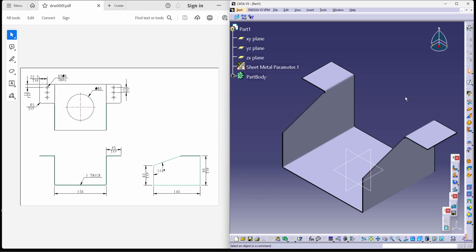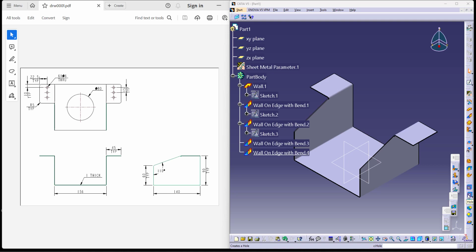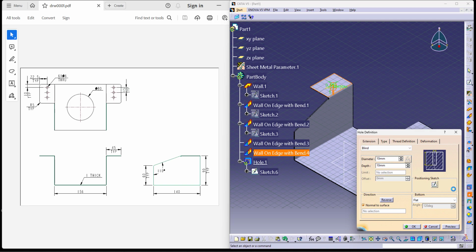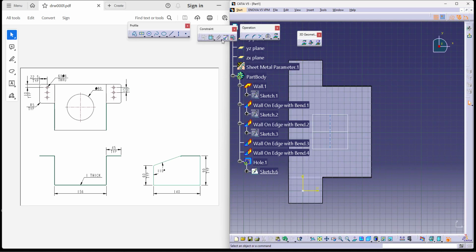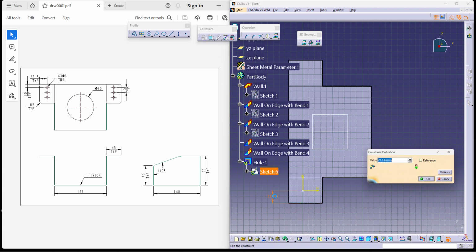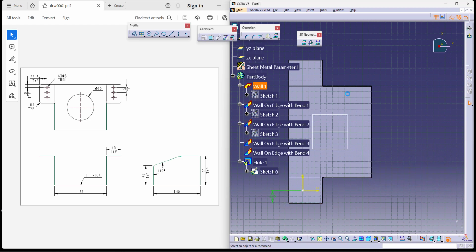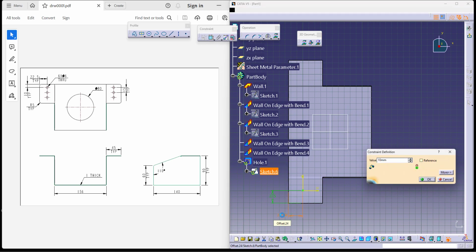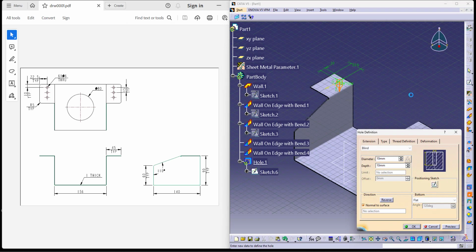Now there are few holes given on the wall for clamping purposes. So let's try to give those as well. I'm just using a hole command. Okay, let me select the face first and then select the hole command. It begins. I have to give the dimensions as per this. I'm just trying to use my constraining part to do so. From the edge it's actually 22.5 and from the top edge it's actually 10. Now the dimension of the hole is 6 and it's up to next.